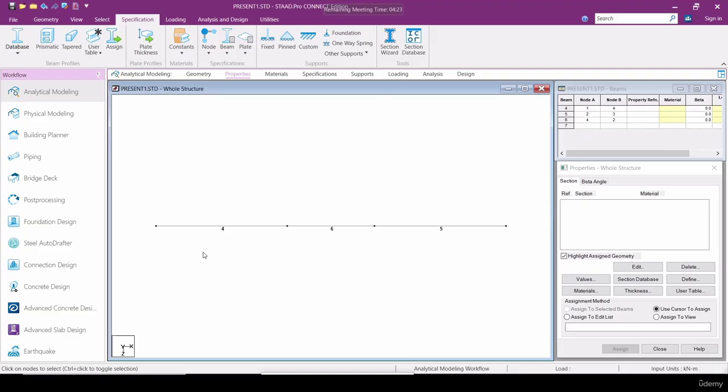So only lateral forces and shear force will be there. Lateral forces due to wind or irregularities in the structure, and shear due to vertical loads, or lateral load components, I can say. So that's why a PEB structural design engineer must try to design a PEB structure with pinned base only.